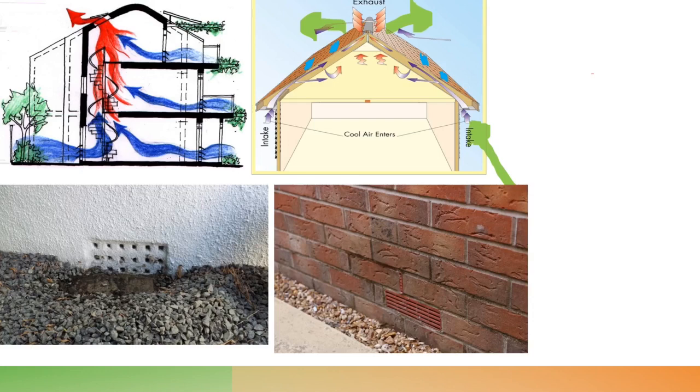The problem is that the finished ground level has risen, which means the potential for damp to penetrate through the brick is greatly accentuated, and of course the air brick is now starting to get covered up. So there are going to be serious condensation issues there, rising damp certainly, leading to lots of human comfort problems in respiratory terms and so on and so forth. But we can look again at that later on.